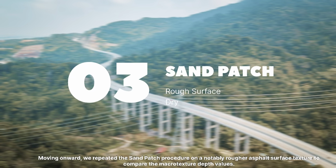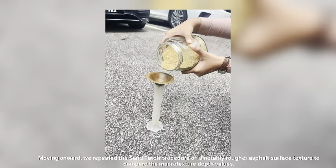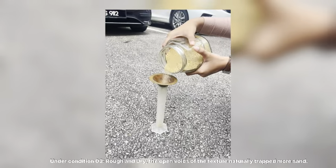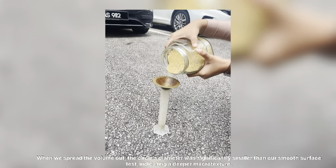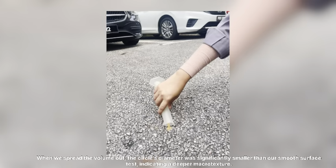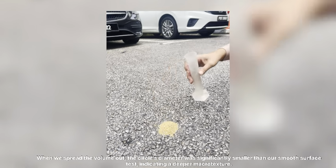We repeated the sand patch procedure on a notably rougher asphalt surface section to compare the macro texture depth value. Under condition 3, rough and dry, the open voids of the texture naturally trapped more sand. When we spread the volume out, the circle diameter was significantly smaller than our smooth surface test, indicating a deeper macro texture.